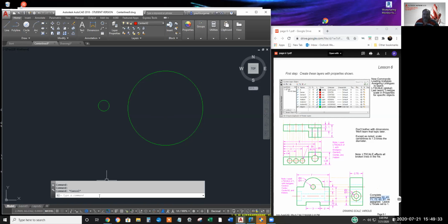Okay, that's done with the LT scale system variable. I can't remember if this is on an options dialog box. But check it out. I'll type LTS or LT scale, enter. And this is the global setting. So if I double it, say 2, enter, all the long lines are going to be twice as long now.